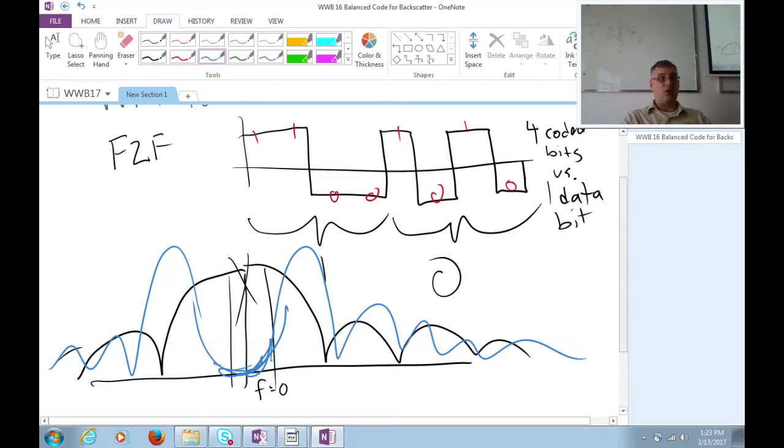And this explains why we can't clock beyond a certain frequency on our computers, right? If power consumption is proportional to clock frequency, but the device isn't changing size physically, then there comes a point where I clock it so fast that I just have too much heat in my circuit, my chip.